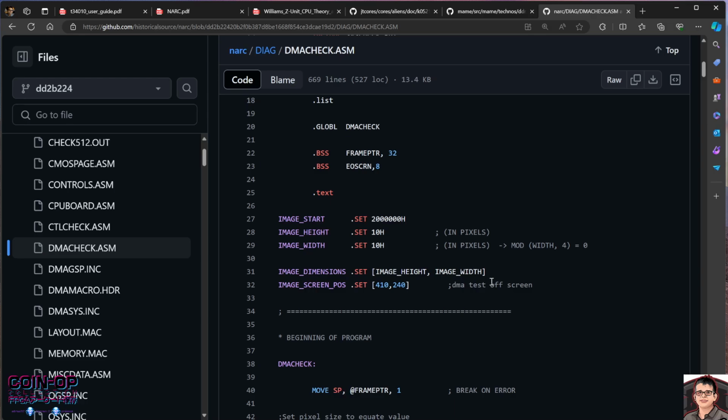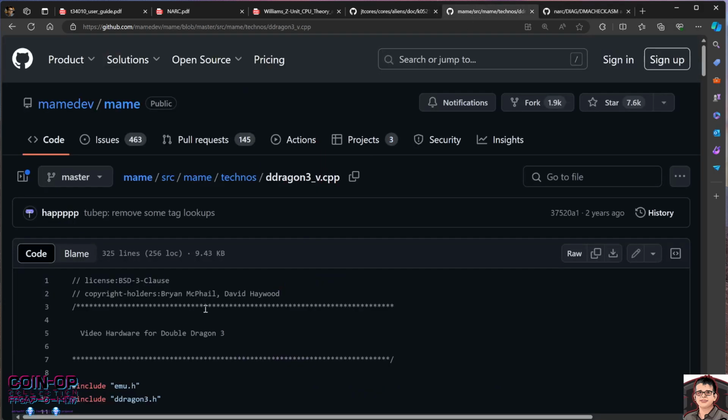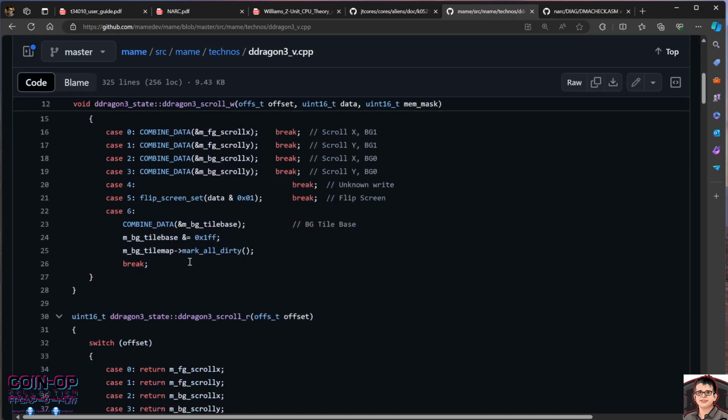Okay. Also, I want to leave you with a note that what you see in MAME is not the be-all and end-all, because it works differently than an FPGA core. With an FPGA core, you often need more information to get it even working, right? So in the case of Technos, I think I mentioned this in some posts, there is a very specific interrupt that operates at a certain rate for input, right? So there's an input polling interrupt, a constant signal that operates at some frequency, right? And that's obviously not implemented here.